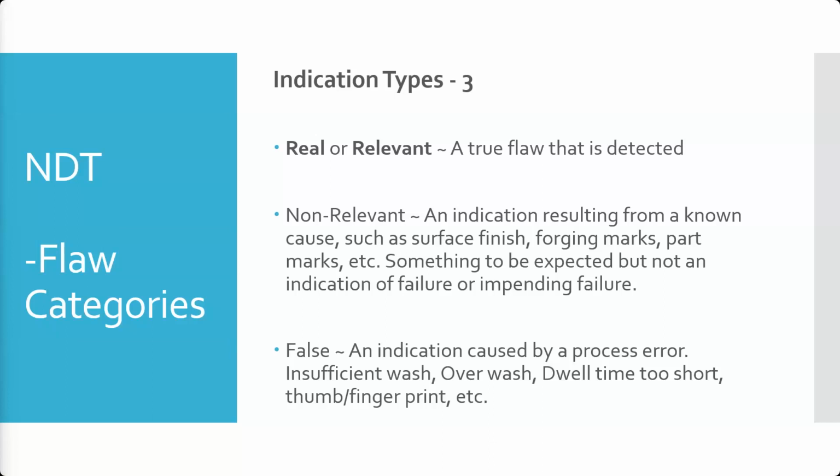It can be because of a mold line. Everyone's seen parts where there's a ridge on them, where the 2 pieces of the mold that made a metal or a plastic part come together, right? That'll cause indications in some kinds of NDT. That's normal. That's part of the manufacturing process that gets left behind. It can be a hole. When you have a hole drilled in something, that's going to trap dye, or that's going to change how magnetic particles react to that area, because the magnetic field is going to be different when you magnetize a part. Or where you have a 90 or some kind of a corner where 2 pieces come together, inside or outside.